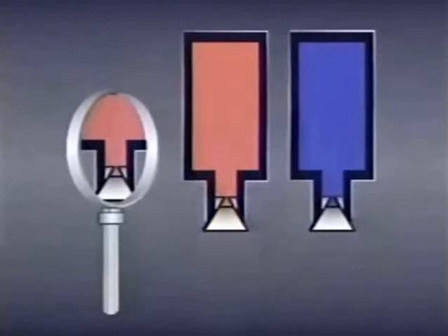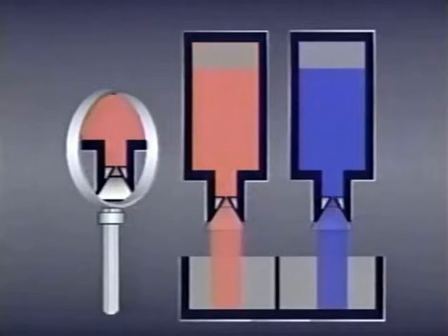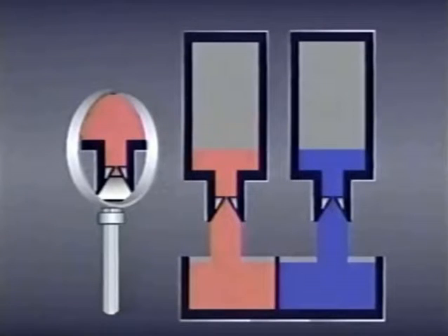Let's say we have two tanks of the same size with identical sharp edge orifices in the bottom. Hot oil is in one, cold oil is in the other. When the stoppers are pulled from the orifices, the cold oil will flow out just as fast as the hot oil. Precision-made sharp edge orifices provide very accurate control of flow rate, despite changes in fluid viscosity.